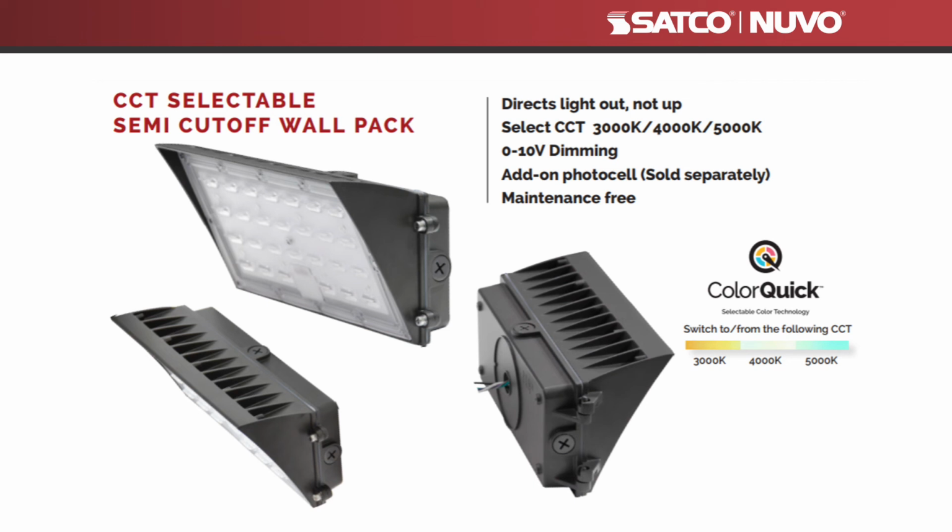Color selectability or color quick has also come to exterior fixtures. Our semi-cutoff wall pack directs light out but not up. The selectability in color temperature is 3000, 4000, and 5000. The fixture is 0 to 10 volt dimmable, and photocells are available.